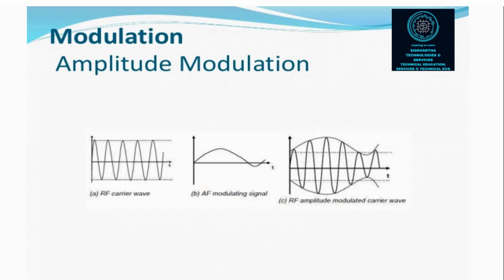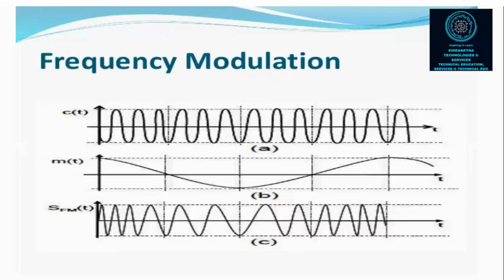Modulation is nothing but mixing, right? Mixing of what? Suppose you want to transmit a sound. You will mix that sound with the frequency specially generated by the oscillator, which will carry it. We call it a carrier. Inside the carrier frequency, you have your main frequency, your audio or any other frequency. That purpose of mixing is called modulation. Okay. Now we'll go to the next.